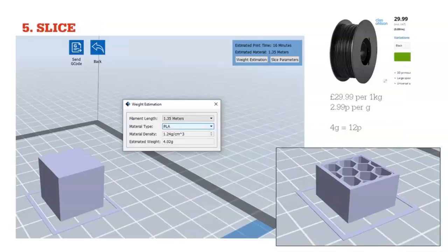If you remember the definition of additive manufacturing, it was making parts layer by layer. So what the software does is slice that model, in this case our cube, into layers. It does lots and lots of layers so that the printer knows what to print. As I said, you can use standalone slicing software, or in this case, I'm just using the one that came with the printer. On the bottom right corner, I've cut my cube in half, so you can see inside what the printer is going to print.